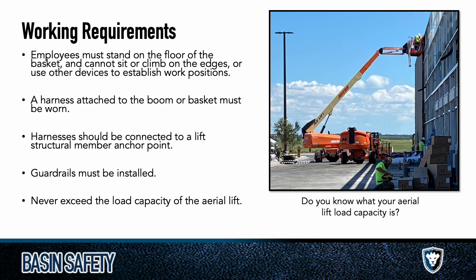Guardrails must be installed and never exceed the load capacity of the aerial lift. This can be tough. Most lifts are designed to be able to carry 2 people, but some of them are only designed to carry like 300 pounds. I know a couple ones around here, they're 350 pound lifts. There's no 2 people standing around here that can both get on that lift right now, right? We don't have 250 pound guys just around, so it's a 1-person lift is essentially what it is.